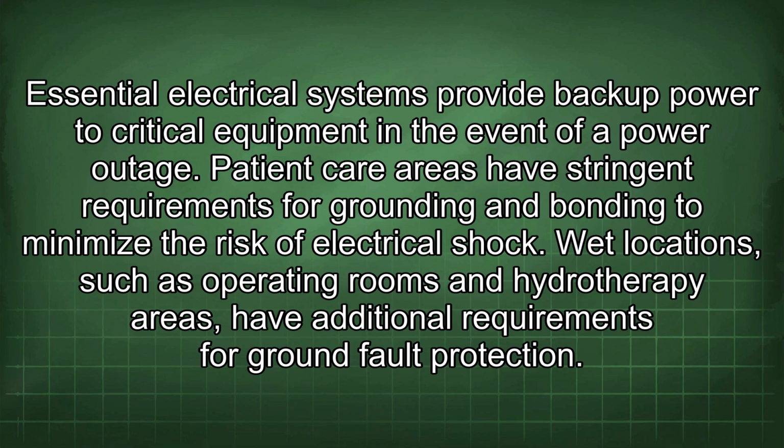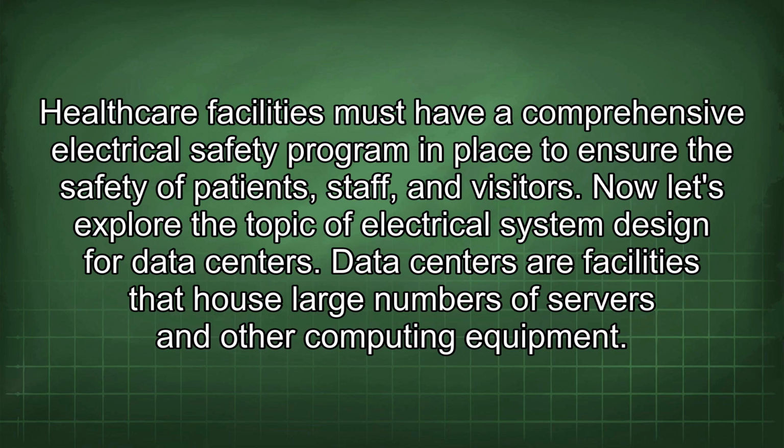Patient care areas have stringent requirements for grounding and bonding to minimize the risk of electrical shock. Wet locations, such as operating rooms and hydrotherapy areas, have additional requirements for ground fault protection. Healthcare facilities must have a comprehensive electrical safety program in place to ensure the safety of patients, staff, and visitors. Now let's explore the topic of electrical system design for data centers.